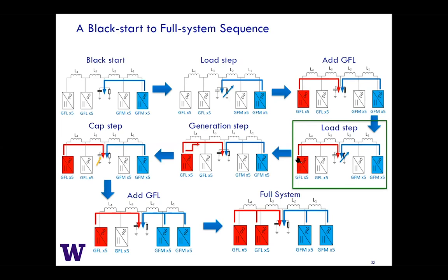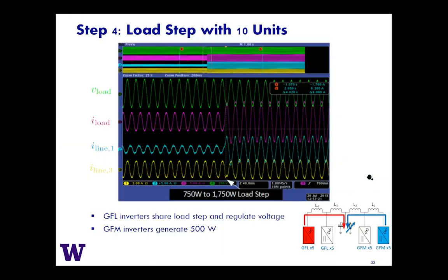So just before I show you the waveforms, the way the following units work, if, let's say these were PV, they would just be injecting the power that is incoming from their PV module and their input. These were actually controlled with a power supply at their input. So they're just following a set point, and they're holding a rock solid power output as if it was just constant irradiance. And so when you have a load step, who picks it up? It's the grid forming units. They act like a slack bus on the system, except it's distributed amongst those units. So let's take a look at that.